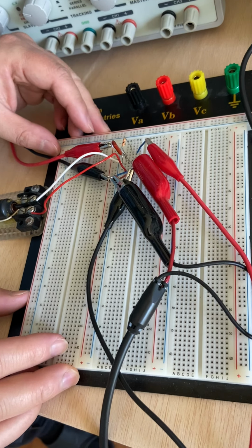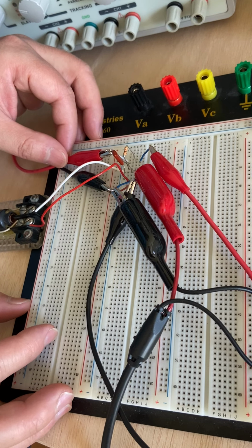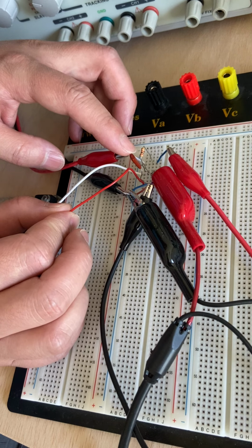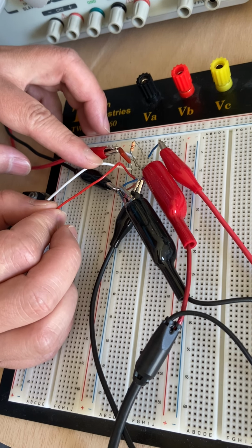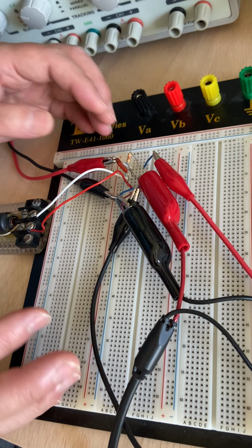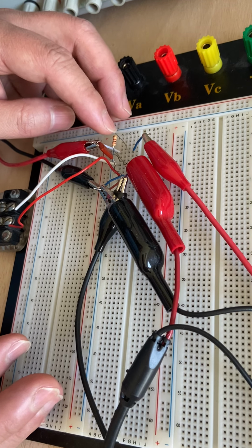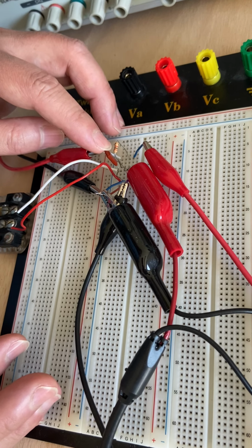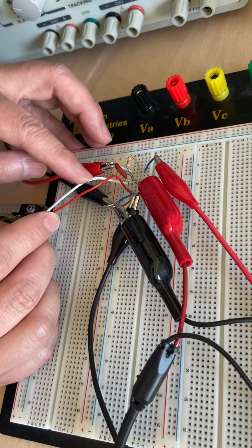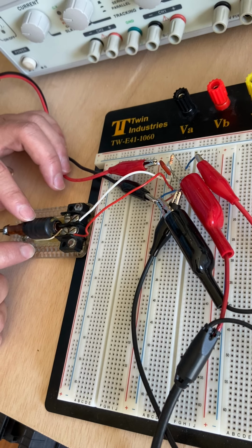So this is for lab 5. We're using the same circuit we did in lab 4. In this circuit, we have one resistor in series with one capacitor in parallel with one inductor. It is exactly the same as the circuit in lab 4, except the resistance of this resistor is 2 kilo ohm instead of 10 kilo ohm. The capacitor is still 15 nanofarad, and the inductor is still 92 millihenry, and its internal resistance is still 130 ohm.